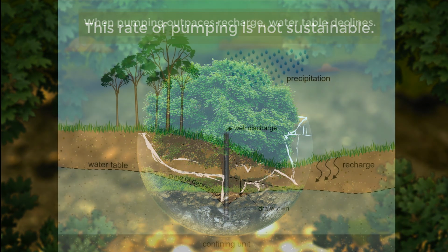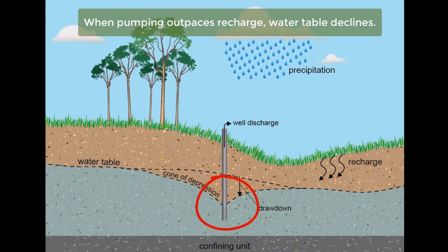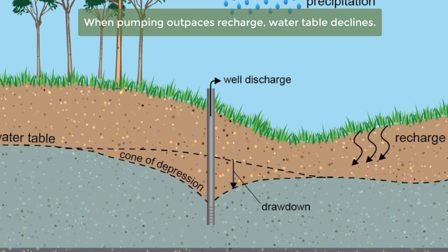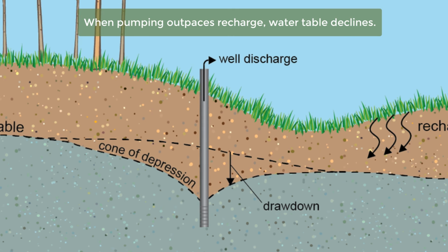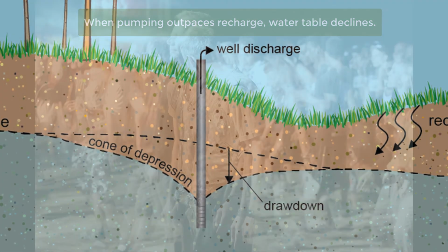the near future. When water continues to be pumped from an aquifer where demand outpaces replenishment, the result is groundwater overdraft and the water table declines. The water table will decline most dramatically near where it's being pumped and diminishes away from the well. As a consequence, a well will have to be drilled even deeper to access that groundwater supply. But the pattern of the lowering of the water table forms what's called a cone of depression, which is most severe at the site of overpumping.